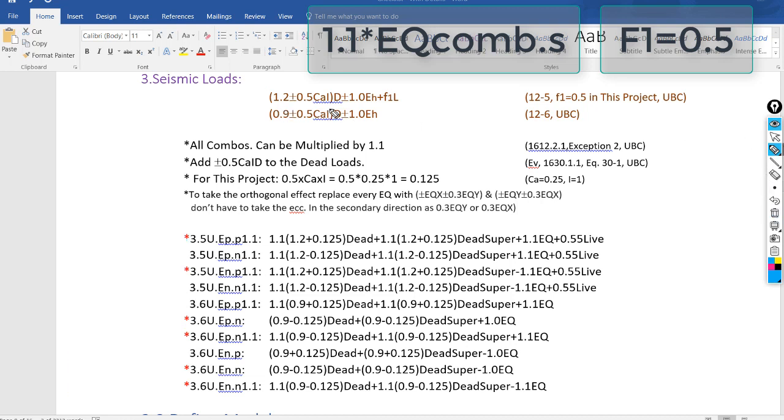As we see, we have two load combinations, but first we know that we design our columns or shear walls due to two worst scenarios. First scenario, we search for the largest vertical or gravity load with moment, and second scenario, we search for the largest moment with the smallest vertical load.